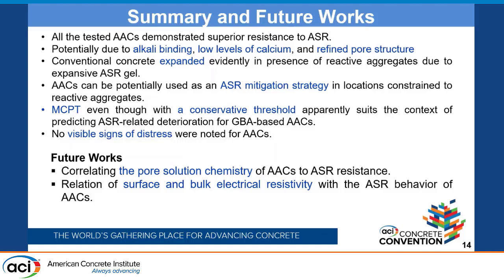The potential reason for the alkali-activated concretes performing so well is that they have high alkali binding in their microstructure, low levels of calcium, and a refined pore structure. So we can say that these alkali-activated concretes can be used as an ASR mitigation strategy in locations where construction activities are constrained to the use of reactive aggregates.